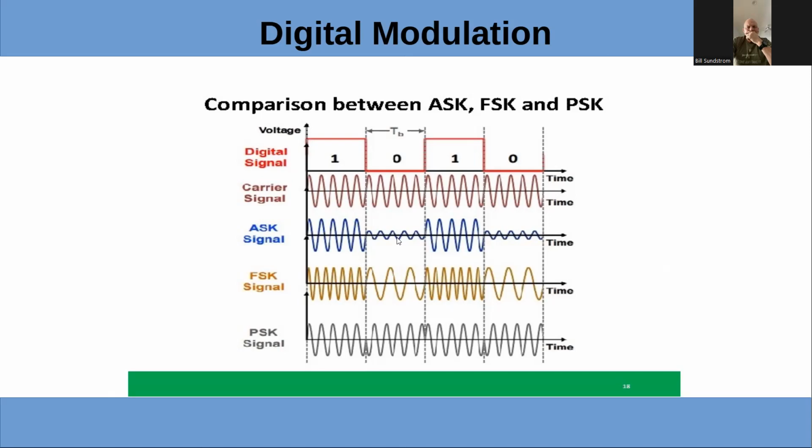It's kind of like Morse code. Frequency shift keying, the 1 is going to be one frequency, the 0 is a lower frequency. Usually, could be the inverse. And then phase shift keying, you can see here is a drastic 180-degree phase shift. Guess it's 180. Looks like it. Says low speed data.